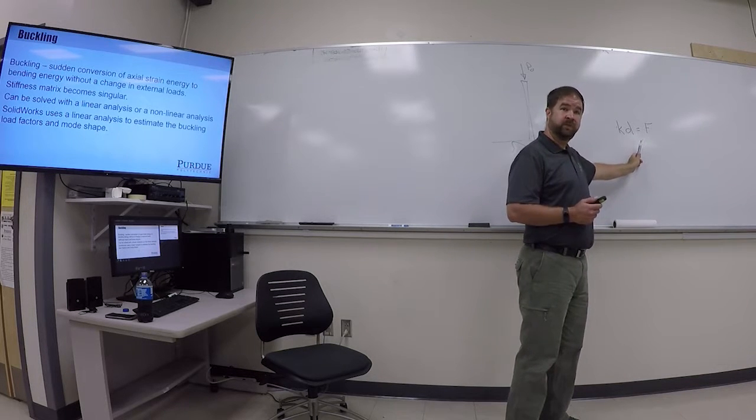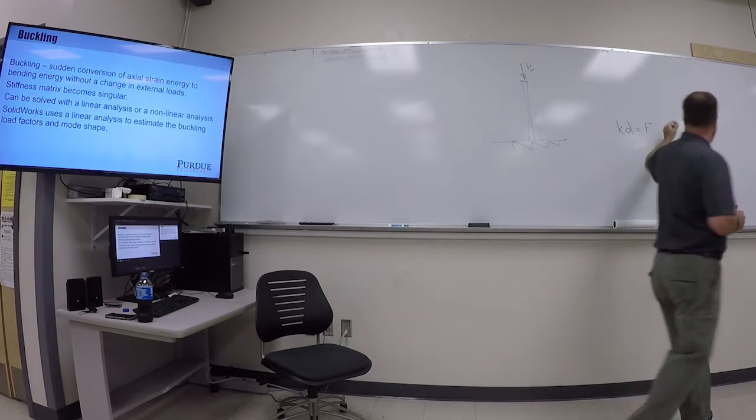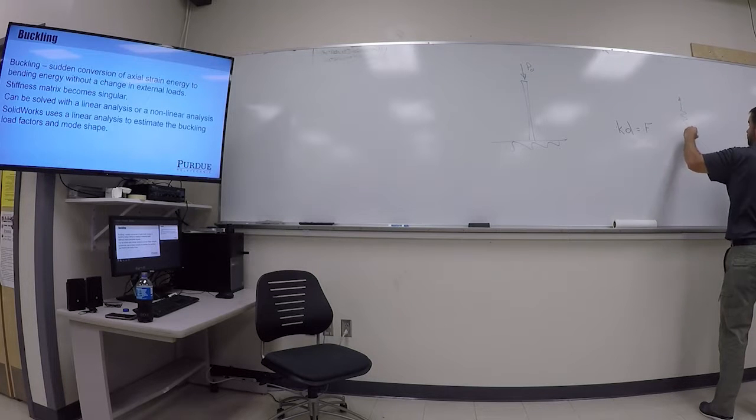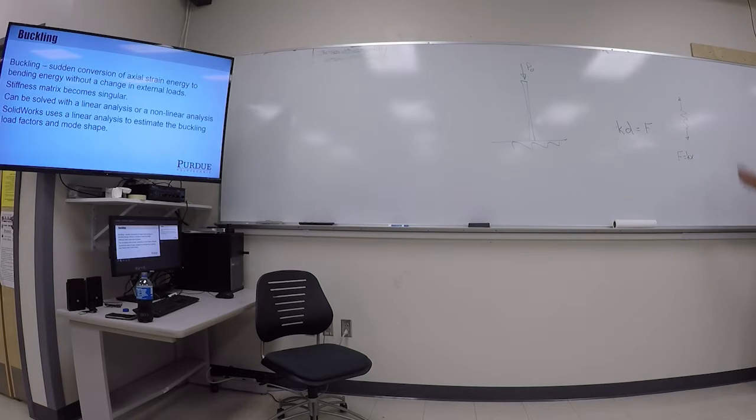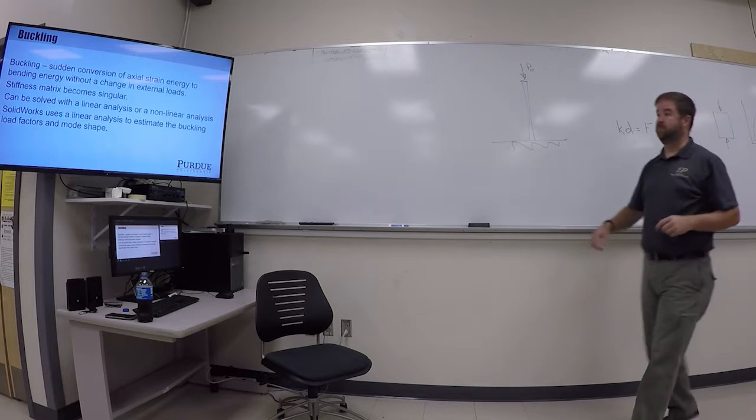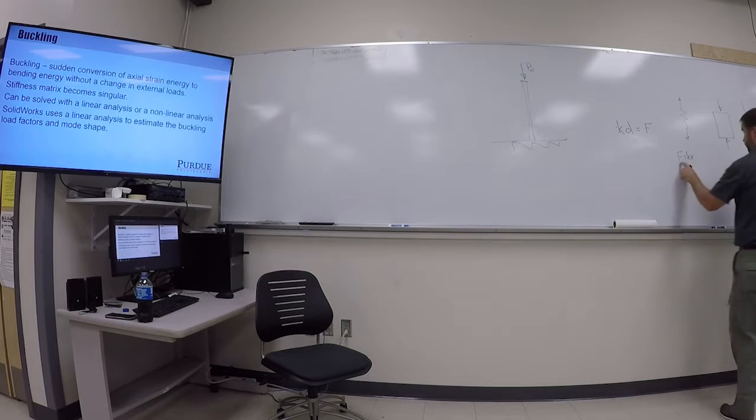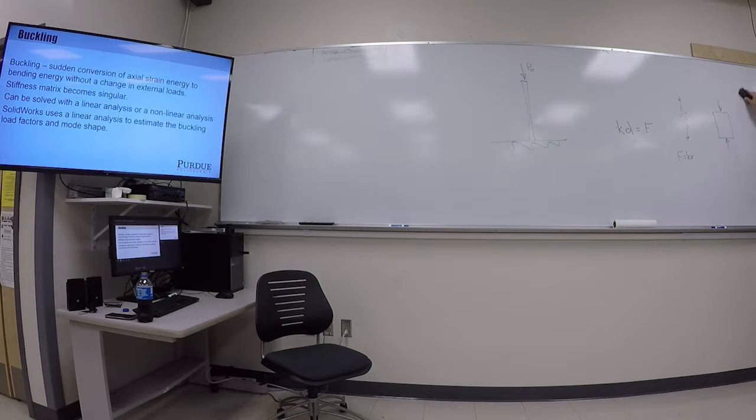There are situations, if we keep it really simple, thinking about springs, a steel spring with force applied to it, F equals kx, that's a linear equation. You deal with a rubber spring, a big chunk of rubber, F equals kx does not apply to a rubber spring. And so typically there is some kind of plot of force versus displacement that looks like this, or something, depending on the type of spring, something else, maybe just not a straight line. So that's a nonlinear relationship. If you're going to model that in finite element analysis, you have to use a nonlinear analysis because there is not a straight line relationship between F equals kx.